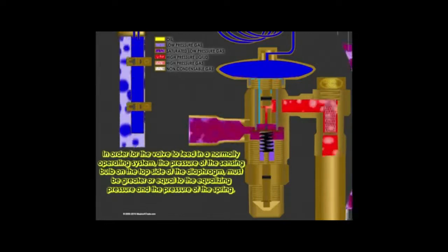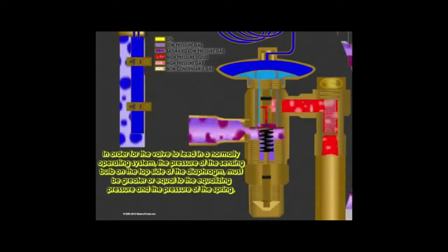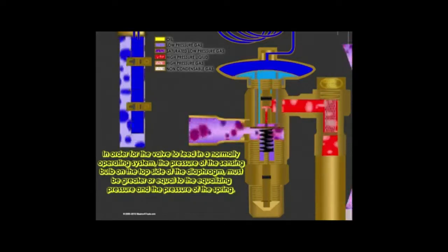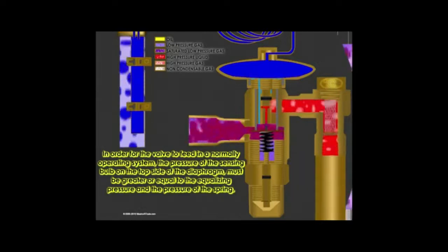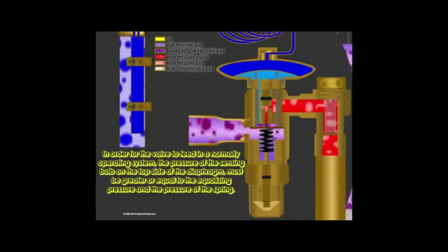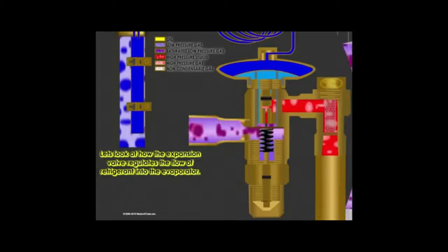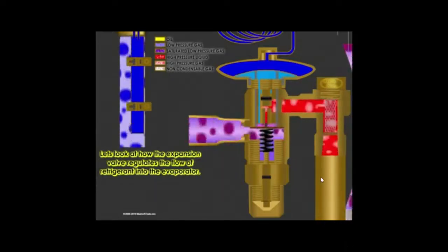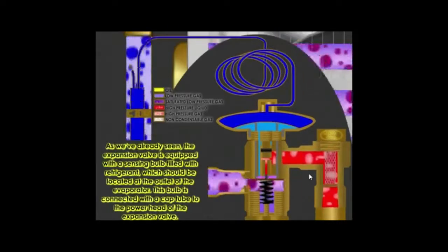As a result of that, the thermostatic expansion valve liquid will not have that much vapor in it, so the pressure applied on the diaphragm will be less, and it will pull up the spring mechanism. As a result of that, the opening between the evaporator and the condenser will close, and less amount will enter into the evaporator. So this way we can control the mass flow rate into the evaporator,